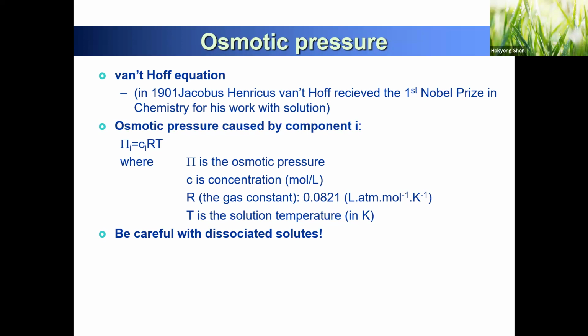But your physical characteristic of viscosity is more important than your osmotic pressure. Overall, even though osmotic pressure is low and the water flux is low, the viscosity has a much bigger impact than your osmotic pressure. So high temperature will have more flux. Even though you have more osmotic pressure, it's supposed to be less water flux. So viscosity is a more limiting factor than osmotic pressure.